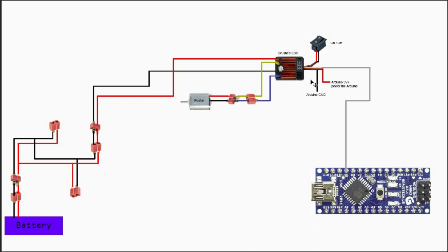Okay, by the way, there is some jumper that you need to set over here to have forward braking, and then to indicate that you are using a LiPo battery. So that's about it.